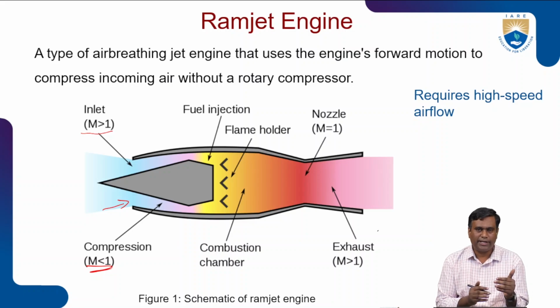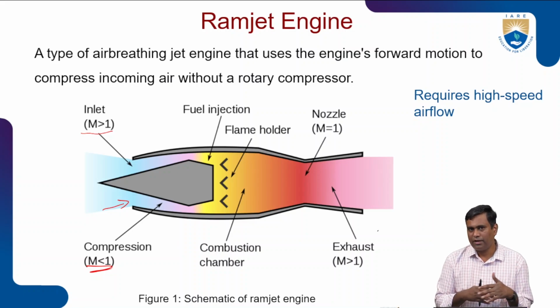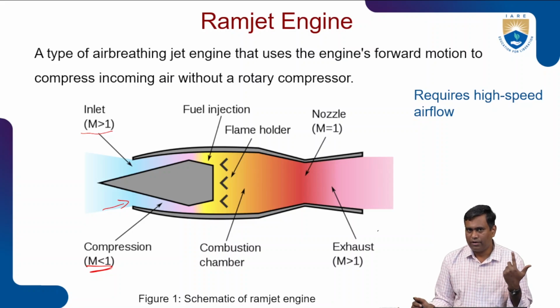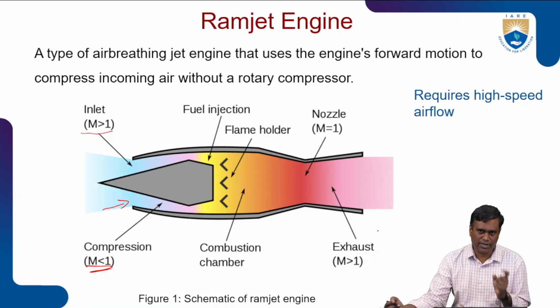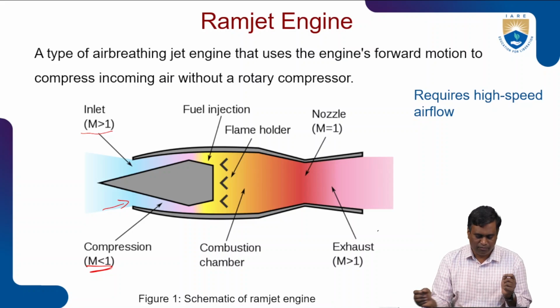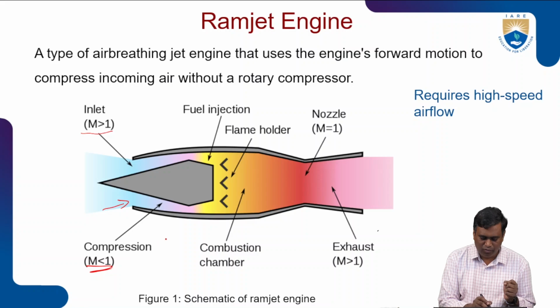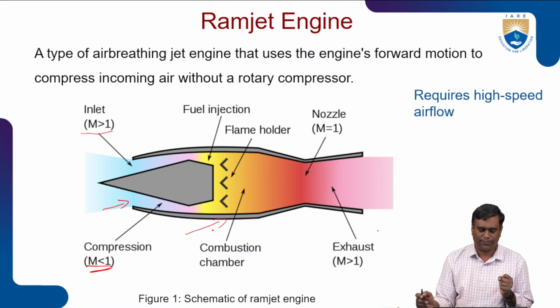So the functions of the inlet are: it should allow high speed airflow in, right? It should handle the high speed inlet air, compress the air and raise the pressure, and at the same time decelerate the flow to make sure that only subsonic flow enters the combustion chamber.